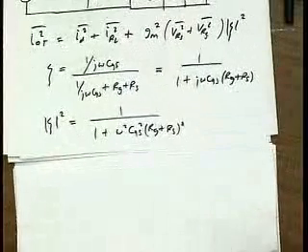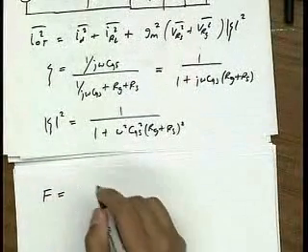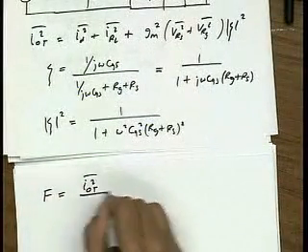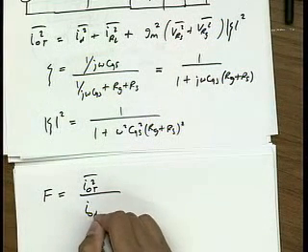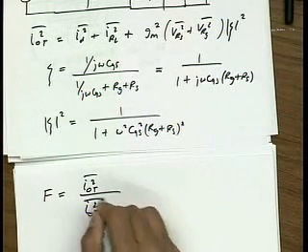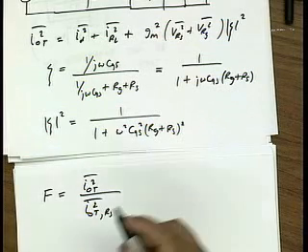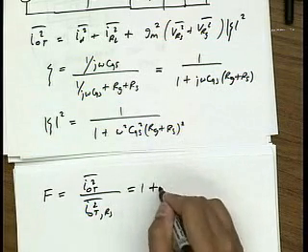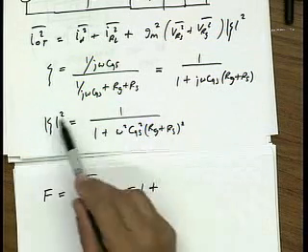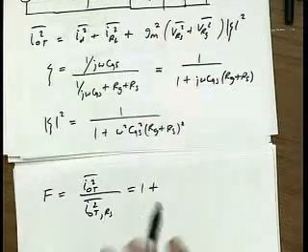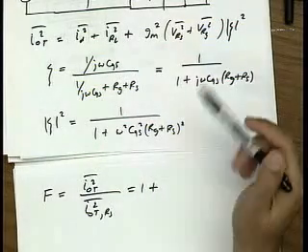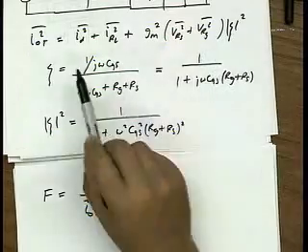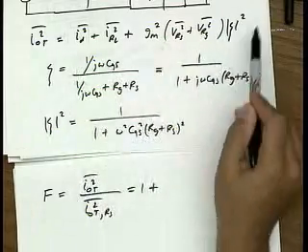Now again I calculate the noise factor. That would be the total output noise divided by the output noise due to RS only. And you can see that this factor cancels out for almost all the terms, except for these two terms. This cancels out, I don't have to worry about it.